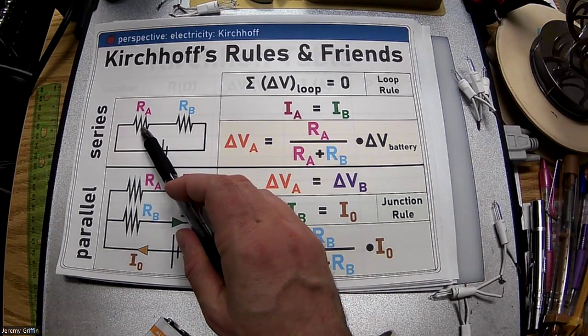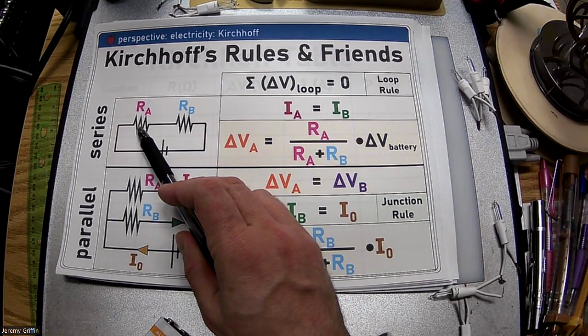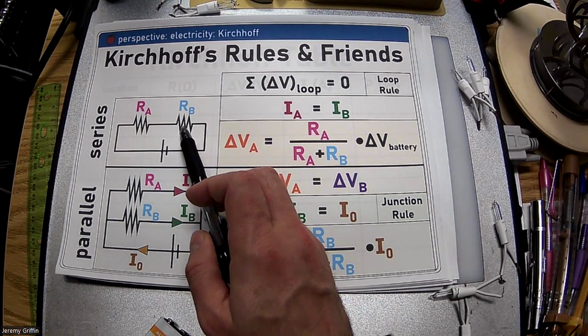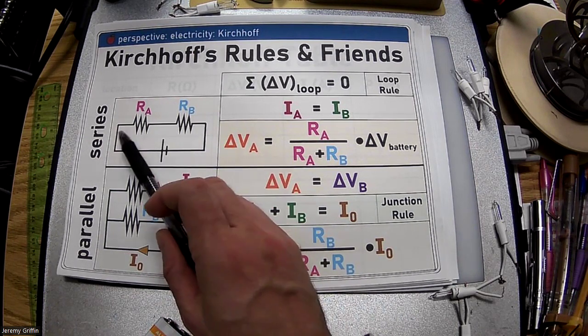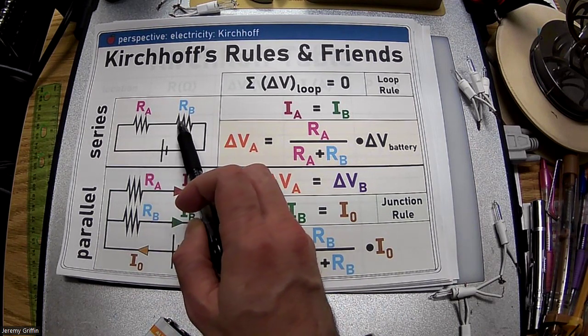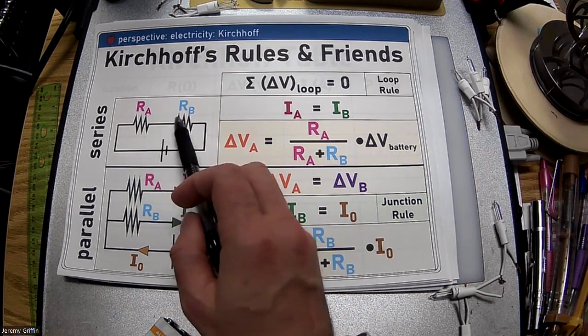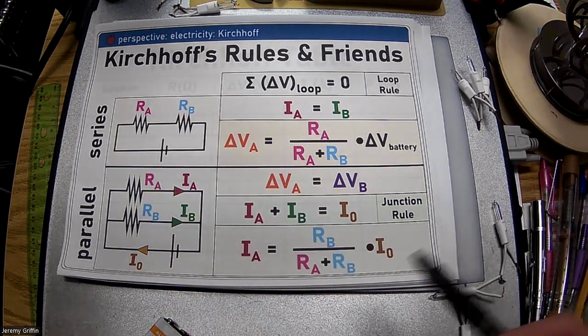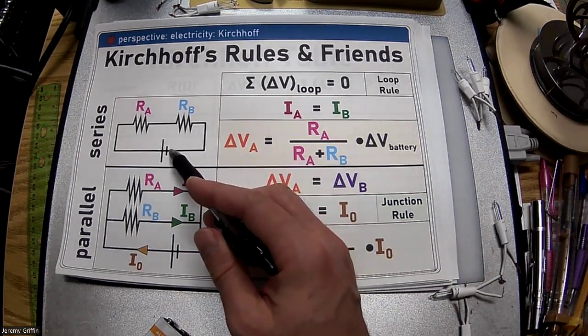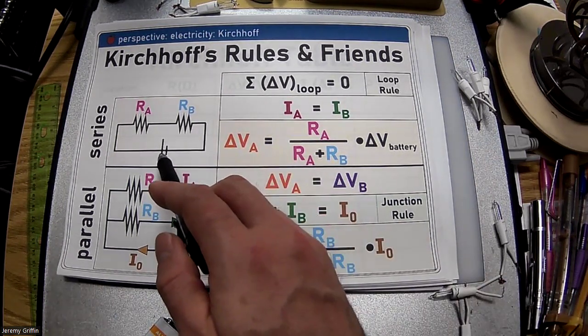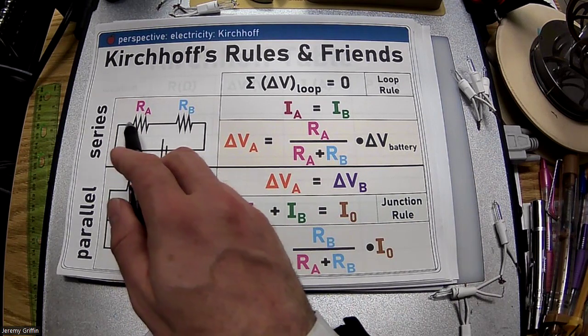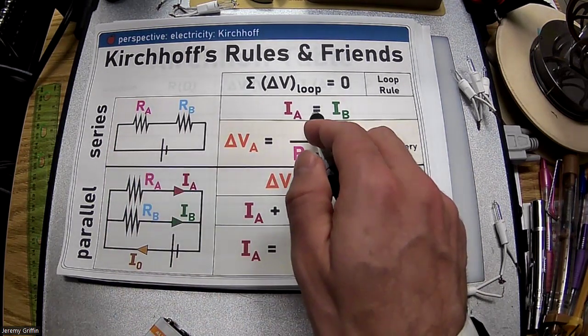Let's see if you guys are following. If resistor A is like 1 ohm and resistor B is like 99 ohms, is it the same number of amps going through both of those? Yes, it is. It's the same flow. Now, if you change out the resistors, it might change how much total current is sent out from this battery to begin with. But say you have so many amps, it's the same number of amps all the way across. Okay, all right.